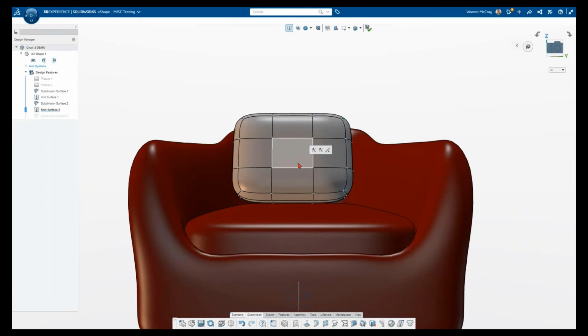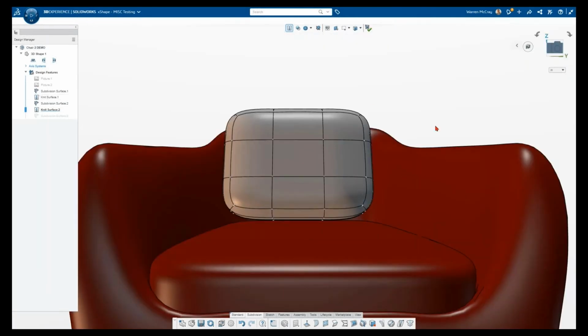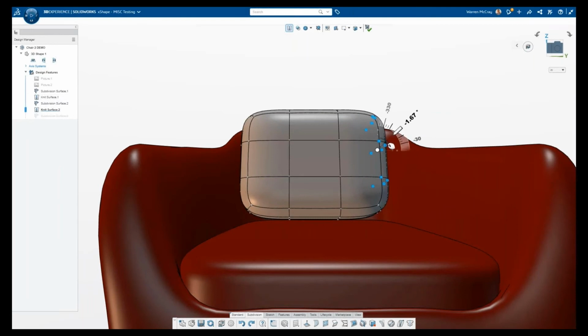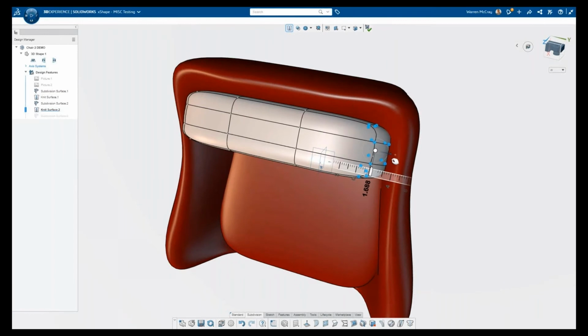So this pillow I'm gonna make a little bit different. I'm going to size it. I'm going to change the corners on this one. And so when I first did this, I really played around. So notice that when I grab things, I pull it and see how it moves and hit undo. And then I see, okay, if I grab all the edges on the right, I could tilt that and change the angle of all those vertices like that. Then I could pull it out.